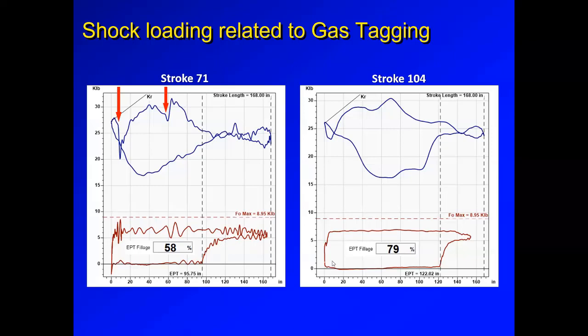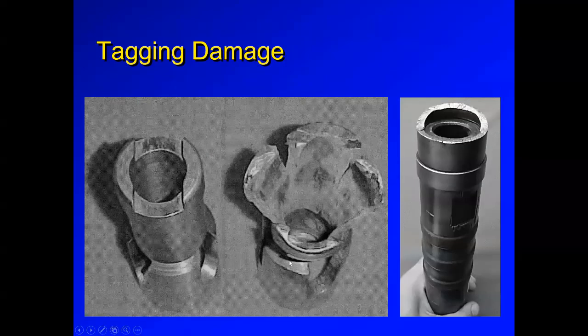So even if you have a rod pump controller, when you pull the card, what are you seeing? Are you seeing the full pump? Are you seeing this beautiful dyno card with just some gas interference? Are you seeing the real well problem when you're pulling a dyno card? So that's why having a more thorough analysis with Echometer is so beneficial.